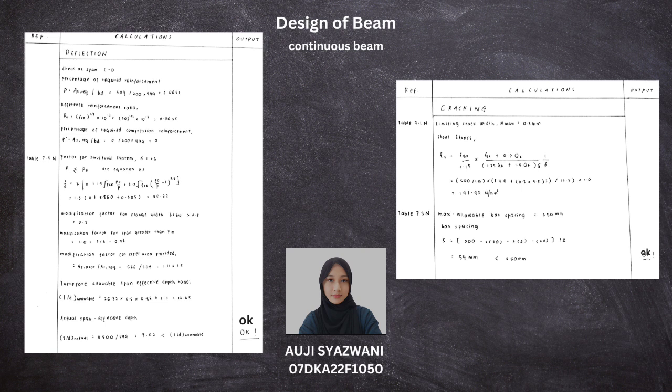Using table 7.1N, I calculated the steel stress and the result was 191.93 N/mm². This value meets the requirement for limiting cracks in the beam.